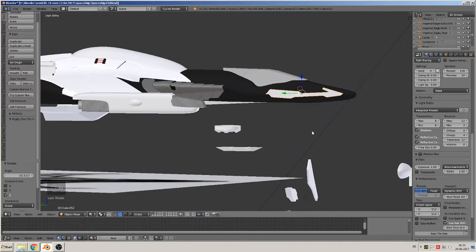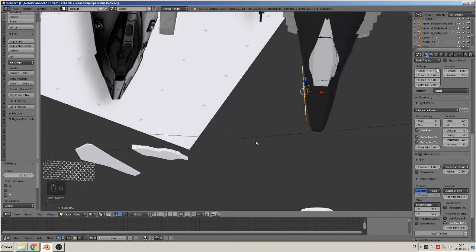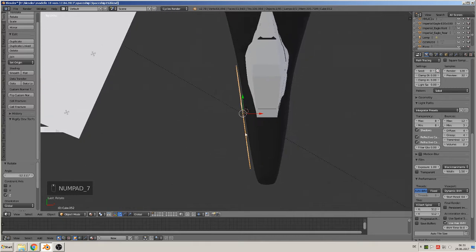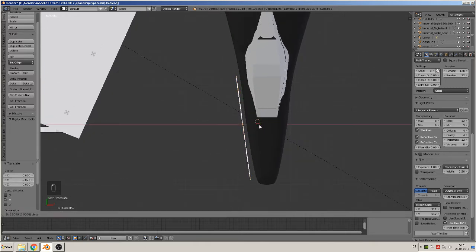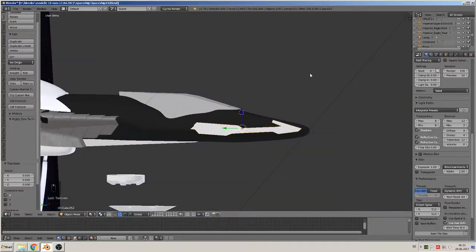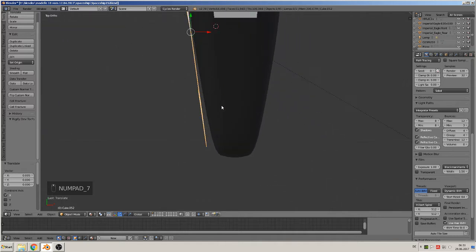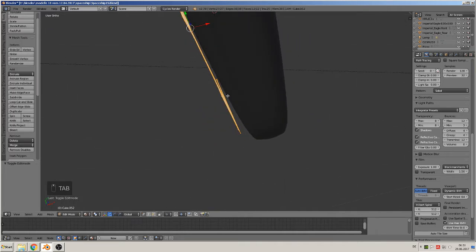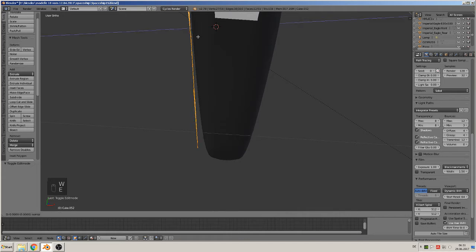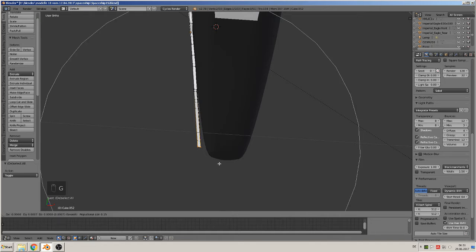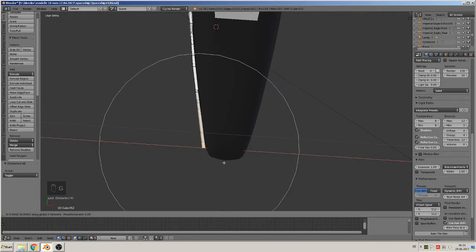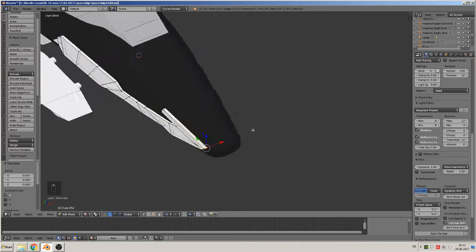I start to use screencast keys so you can see here what I type. So when we look now from the top, we see that we are near on, but not completely. So that means we have to tweak a lot. And that means we go in there and extrude it first time. And then we take the front. And with proportional editing connected, we grab X. So we bend the front to the ship.